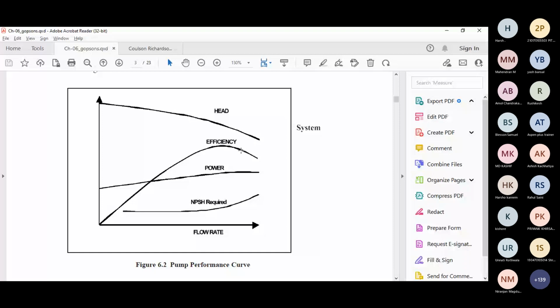Initially आपका power zero है, efficiency zero है, because some of the power is utilized in just starting the pump. So as soon as you open the valve, your power is used. Some of the power is used for the flow rate of the pump, plus to increase the head of the fluid, right? Power के calculation में क्या क्या आता है? Head, density and the flow rate, right?